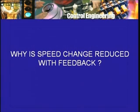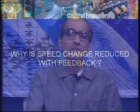We will find that the speed change will be less with feedback than it was without feedback. With 230 volts constant armature voltage, there is a certain change in speed; with this feedback arrangement, for the same change in the load torque, the speed change will be reduced.